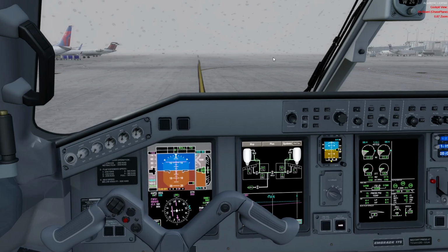So we're now pushed off the gate, and we're about to taxi out and take off. Now, I want to discuss first of all, what is icing condition? So I'm separating this from whether or not the ice detector has detected ice. Quick reminder, it's not going to happen on the ground. So what do we call icing condition? Anytime we see visible precipitation or moisture when we're at or below 10 degrees Celsius.